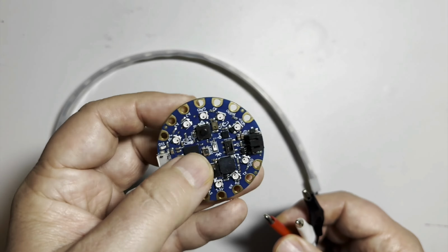Now, in this NeoPixel strip, our power is going to go to the VOUT pad. The lights will work if you attach power to either of the 3.3 volt pads as well, but VOUT will take advantage of the full power you get when you plug your board into a USB or battery. NeoPixels can handle a higher power, so we're going to use VOUT. Ground can go into any of the ground pads. There are 3 on this board. And for signal, on this strip, that's the white wire. Where we clip the signal wire is going to be associated with the code that we write. And we're going to write code assuming that it's clipped to the A1 pad, so let's clip it there.